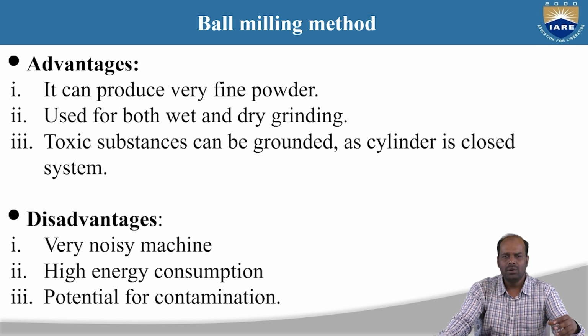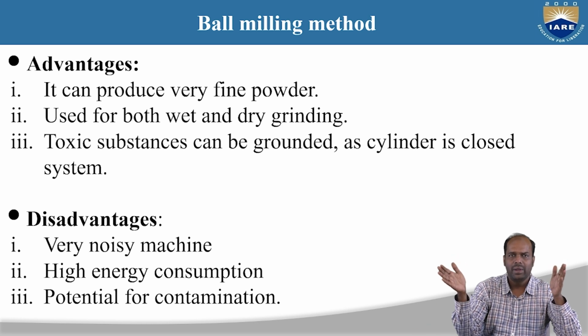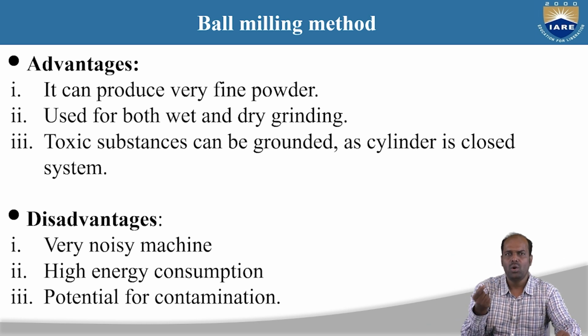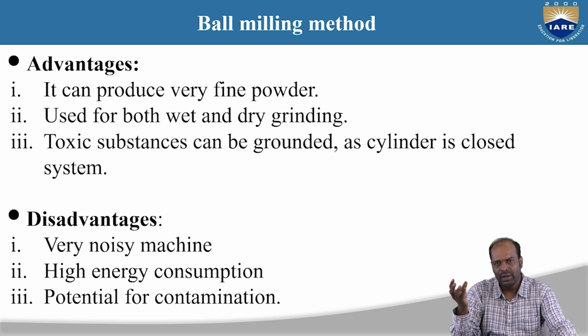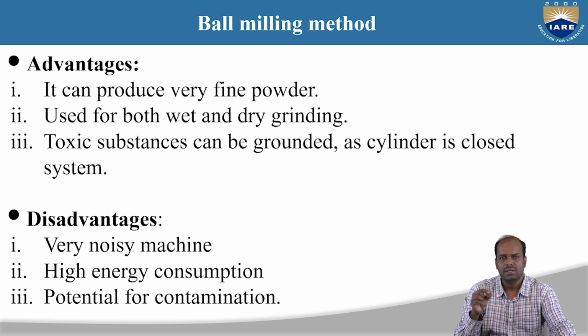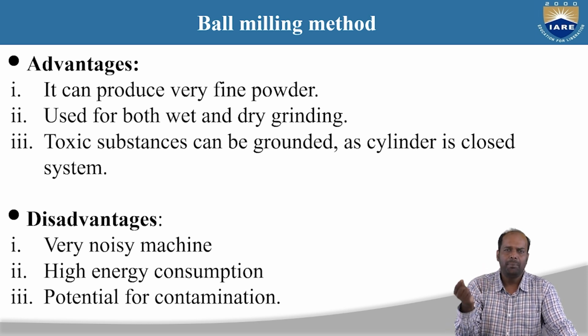Disadvantages: because we are grinding larger particles into smaller particles, from the grinding point of view we get more noise and high energy consumption. Also, the balls can contaminate the precursor, the material we have taken. So there is a chance of a little bit of contamination, but with precautions we can avoid contamination also.